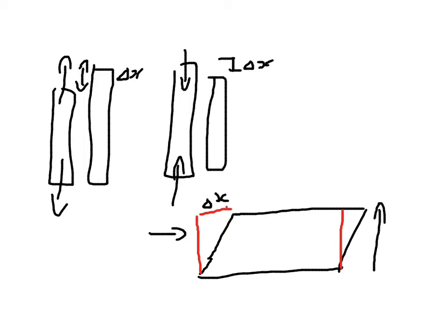Your delta L in this case, delta X, will be the amount of tip in the direction of the force. Your original dimension will be the height of it. So that's slightly different in knowing where those numbers come from. So delta X is the amount that you're tipping it. X is the thickness of the material that you are shearing. A is the area that is in contact with the material. So it would be the top surface on this, because the shear, which I haven't drawn very well, is being applied across the top here. So it's like rubbing your hands together. The shear is between the two surfaces. So A is the area of the surface under contact.